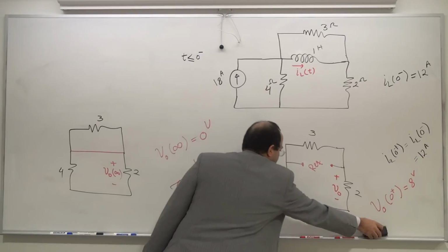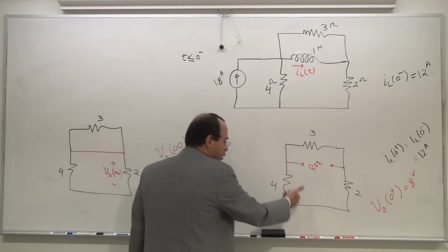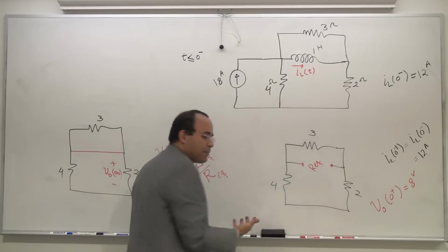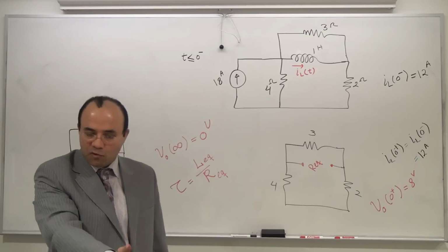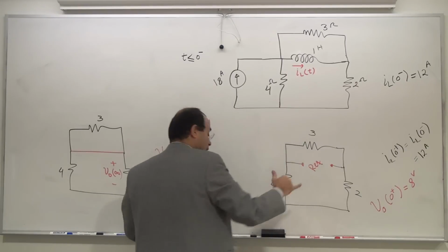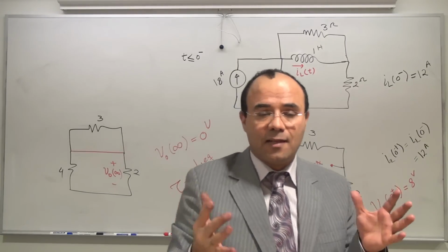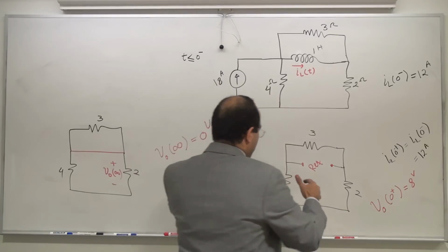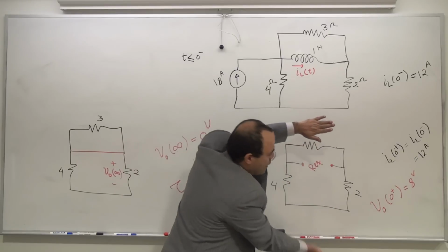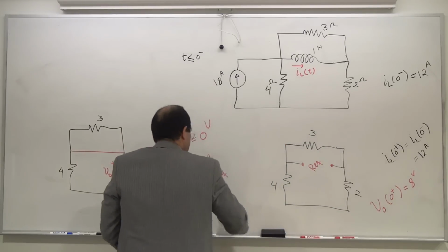I have here, then I don't have the voltage, that's not the concern anymore. If I do have an independent source, I'm going to shut down the independent source. Voltage source becomes short, current source becomes open, but now I want you to pick up this. Now you remember initially back in chapter 2, it might have been difficult for you to see this in parallel, but through the exercise you can see it. If you grab this out, you can see 2 and 4, 6 and 3, 2 and 4, 6 and 3, that would be in parallel.